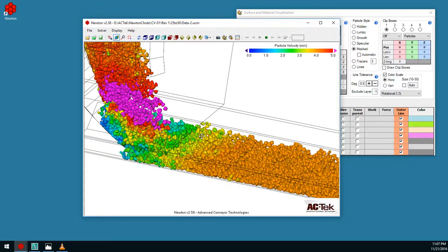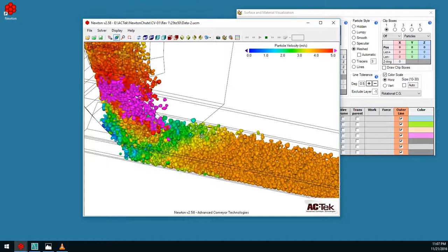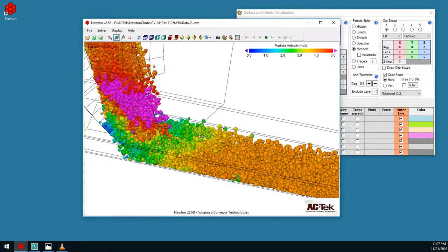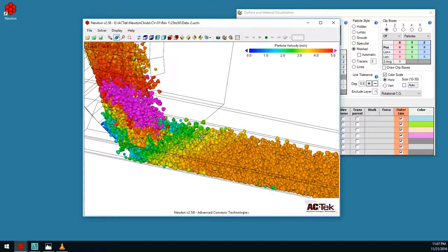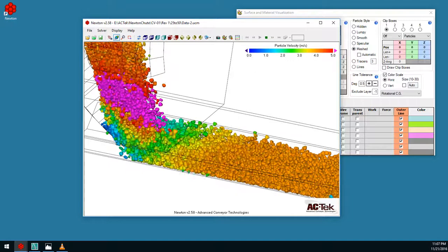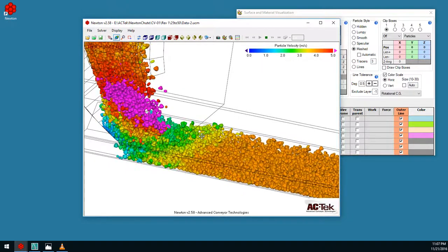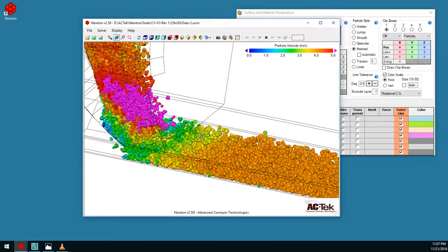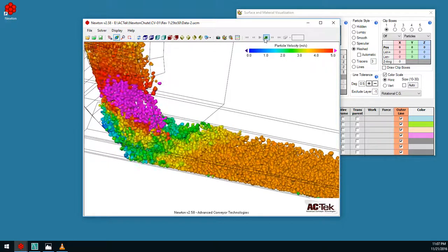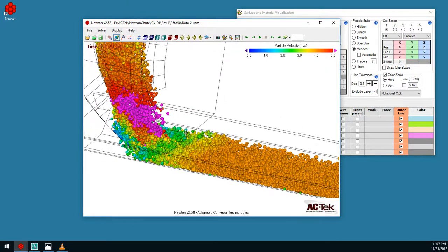However, in DEM, a lot more impact is going to come from what you use for the material properties themselves. As we were just talking a minute ago about testing and the different types of testing to be able to get those adhesion and cohesion effects, they are going to have a huge impact on your simulation, much more important than the actual shape of the particles themselves.